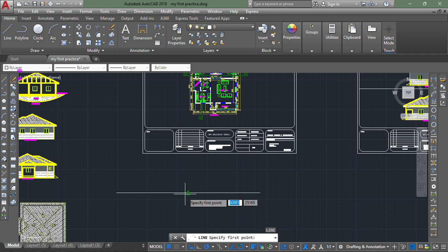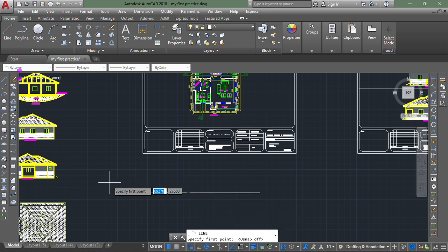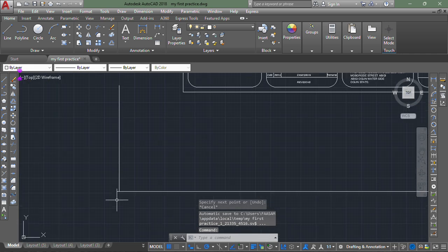And also if you come to the middle here, it shows us our midpoint. But let's assume I switched it off now and I want to draw a line here. See that the box has gone. No matter the kind of line I'm drawing, you can't tell if it is joining or not. Because let's assume this is the end point, right? And let's draw a line. Now let's zoom in. Do you see that it's not joining at the end here?